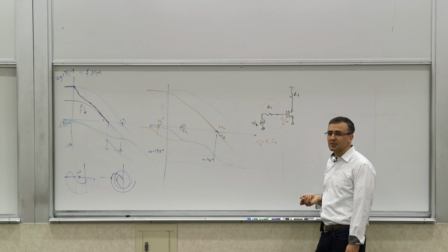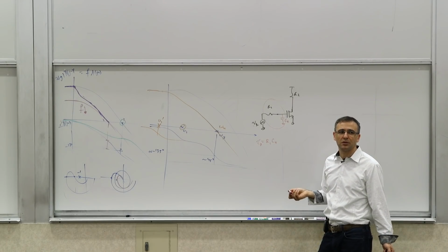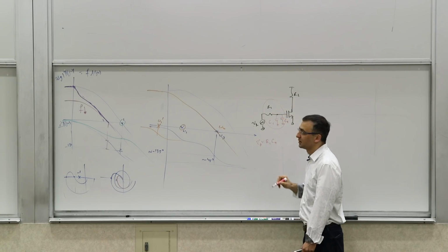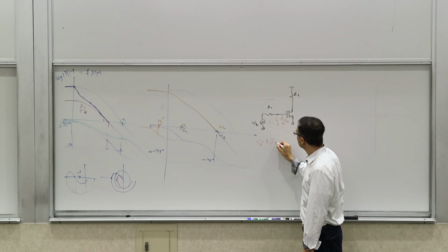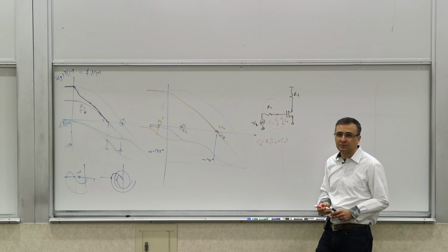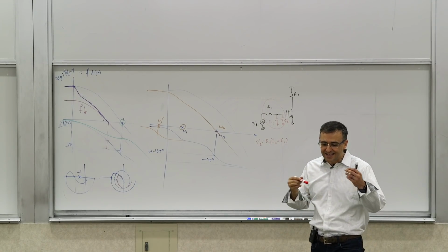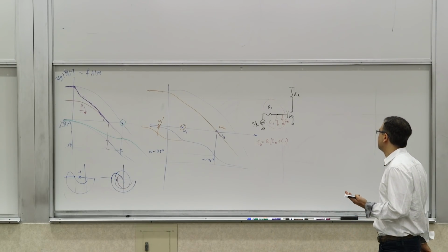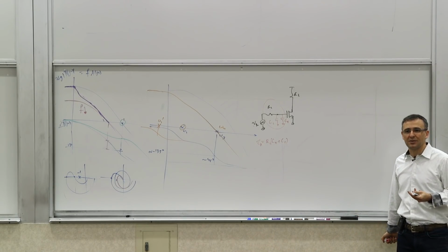And how can we increase this tau pi? What's the simplest way to increase this thing? Well, the simplest way is to add an extra capacitor, right? Then your time constant becomes C1 plus C pi. So if you're adding an extra capacitance, you intentionally are lowering the bandwidth of this thing, which is not the best way of doing it, and we will see later.